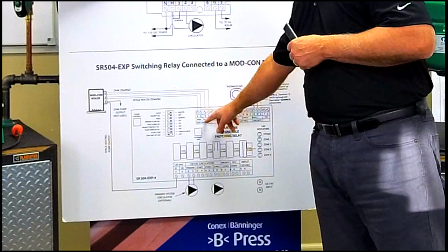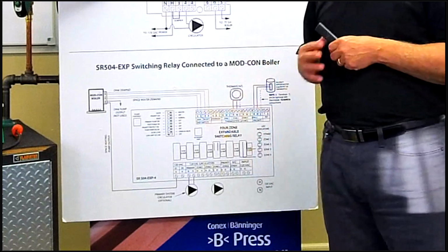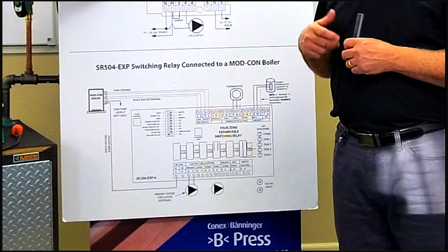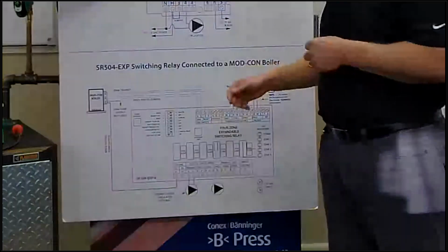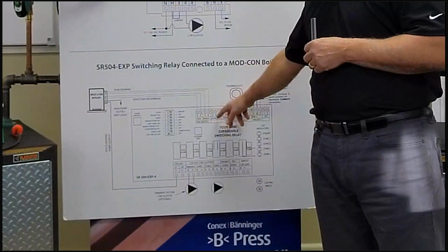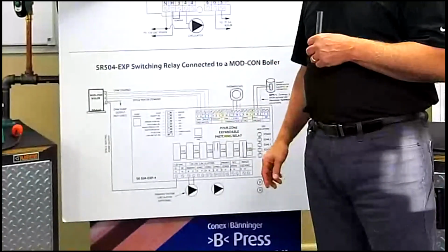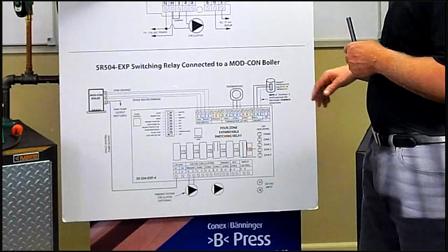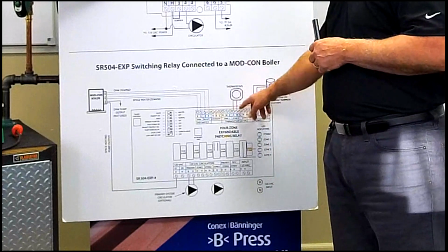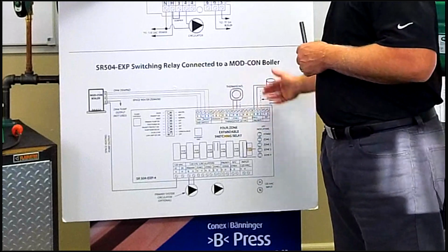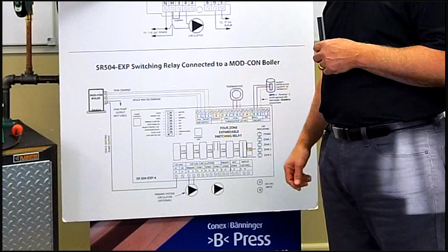We also give you another end switch on here. So if it is a condensing boiler and it has a second TT on it for domestic to tell the boiler to high fire, we give you that end switch there too, so you can bring it to the boiler. Makes your wiring simple and easy. Okay. R, W, and C, like I just alluded to, so I can give constant power to our stats. And again, the last zone is our priority zone.